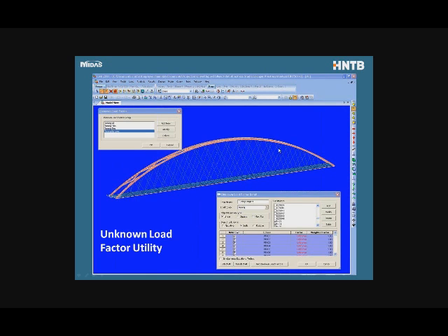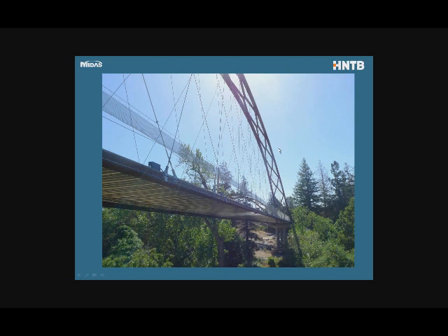Here we go. So if you do it correctly, at the end you get a bridge that's straight as an ironing board, like Happy Hollow. You can see the extremely slender deck, very straight, cable forces wherever we wanted them. You don't want to be too picky. It's hard to get the cable forces just right, so you don't want to design too close. But the geometry we can get within a fraction of an inch easily.